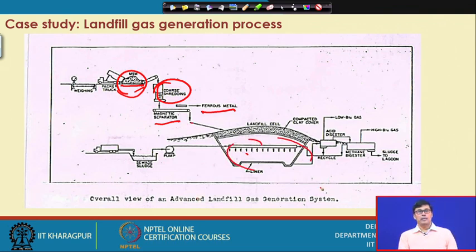Now there is an international sanitary law. International sanitary law says that whenever you put any kind of organic waste in the landfill, this should be covered with a 6-inch clay layer within 24 hours. Otherwise, the gas will be generated from the solid material and pollute the atmosphere.